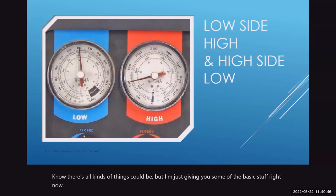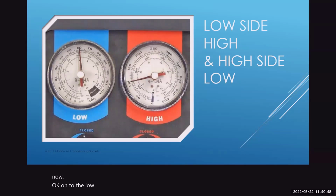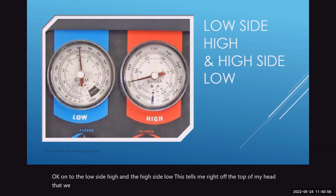Okay, on to the low side high and the high side low. This tells me right off the top of my head that we have an internal compressor fault. This may be a valve problem in the variable type compressors.